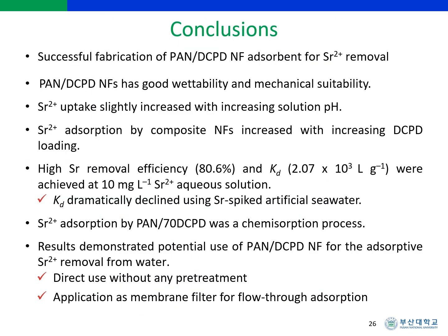Here are the conclusions of the research that I just shared with you. A potential application of a new composite nanofiber adsorbent for strontium uptake in water was successfully demonstrated. More manageable strontium removal would be achieved using the PAN DCPD nanofiber adsorbent. The fibrous adsorbent material prepared was mechanically suitable, hydrophilic, and macroporous, providing good DCPD-strontium contact while preventing DCPD particle loss during adsorption. The composite nanofiber adsorbent exhibited stable adsorption performance in the pH range of 6 to 10.